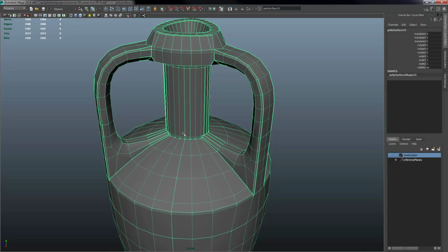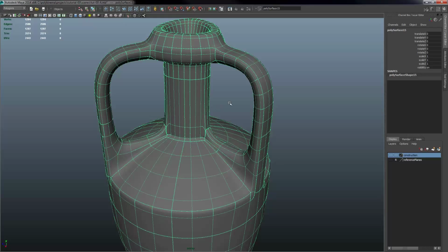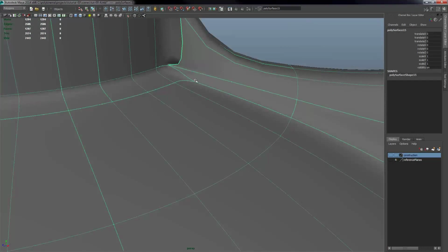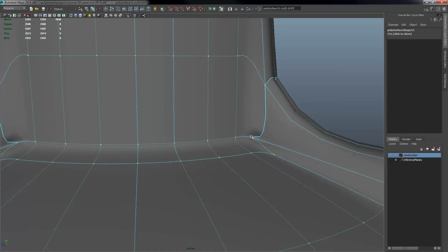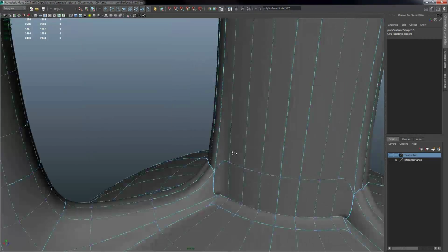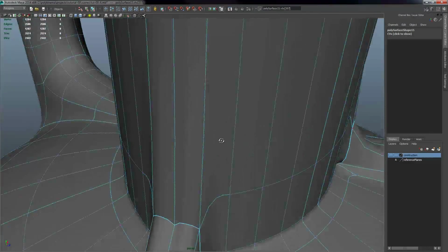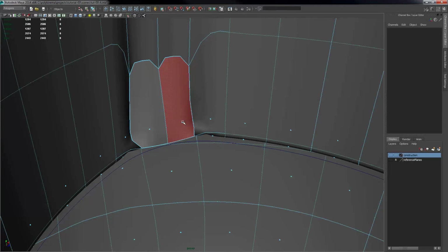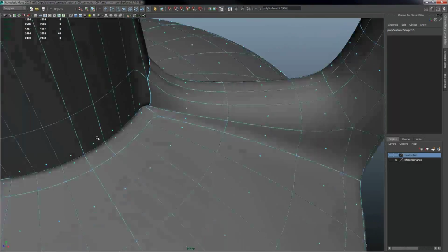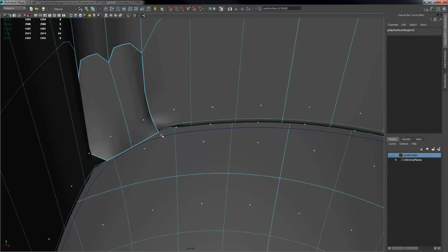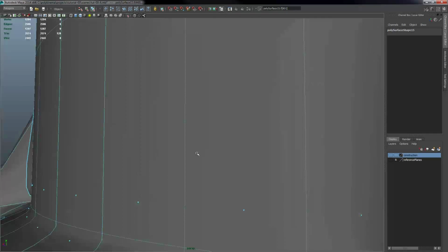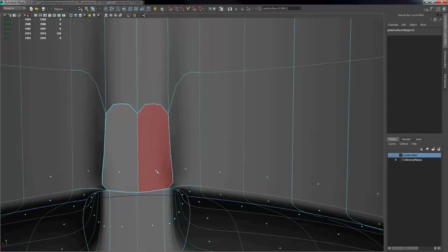So I can have a look at what these bevels are actually doing. It might show me any errors as well, just by hitting 3 on the keyboard. I can see down here we're having some errors with mesh, and again it's because the faces along there weren't deleted prior to the vertex merge that we did.